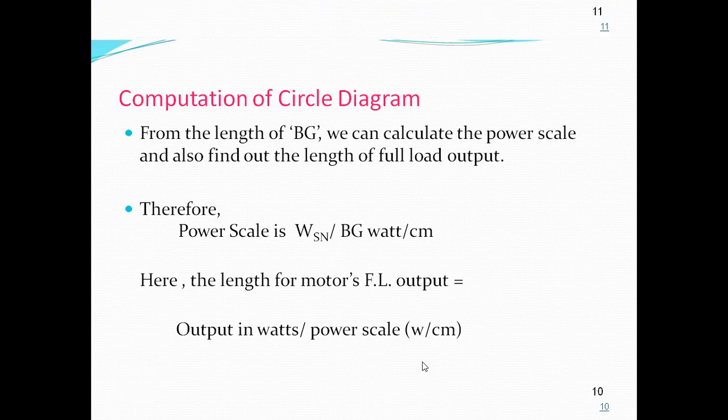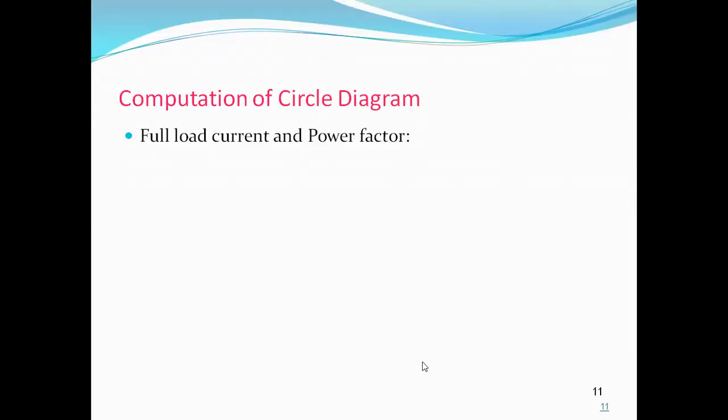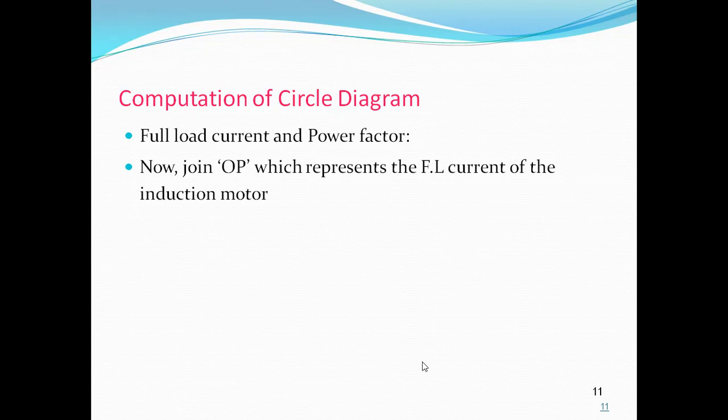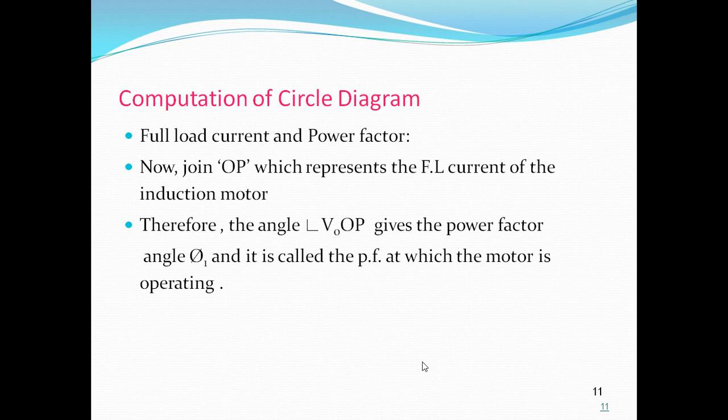So the full load current and power factor: OP represents the full load current of the induction motor. Therefore, the angle VOP gives the power factor angle, that is phi 1, and it is called the power factor at which the motor is operating.